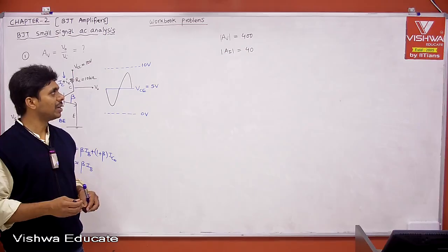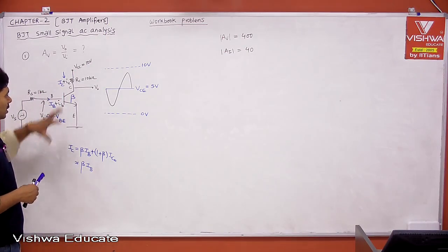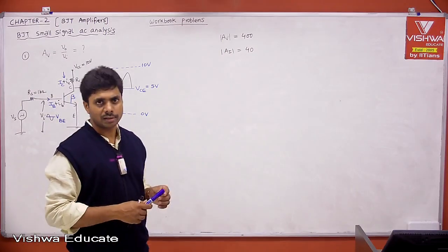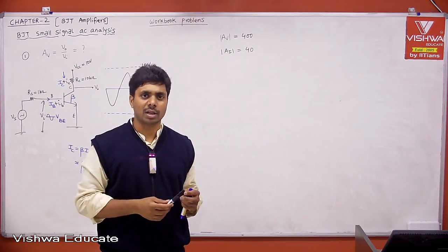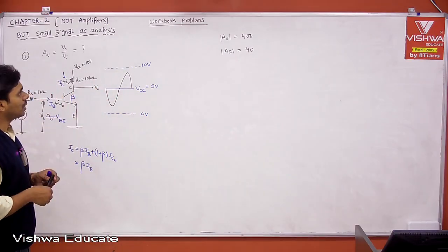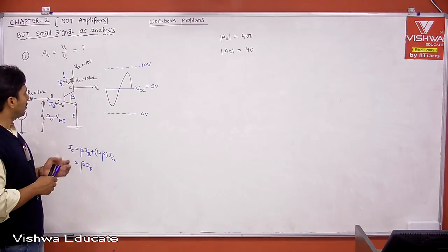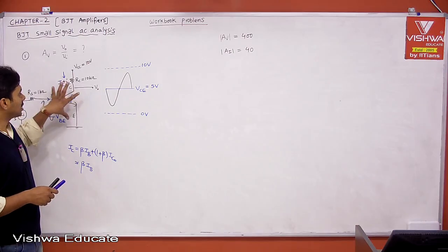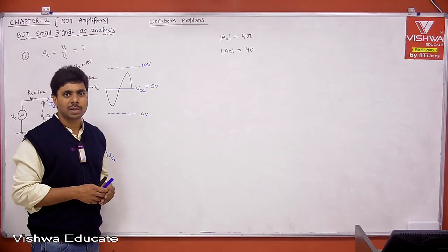Okay, then let me ask you. Definitely, if you want to improve, you can improve voltage gain from a single stage amplifier, maybe from 400 to 500 or 600. But we cannot get 400 to 40,000. We cannot get that much, right? Therefore, a single stage gain of 400 is not enough to get huge gain. Definitely we need two stages. When you take two stages, single stage gain 400, and if you take one more stage, 400 into 400, a multi-stage amplifier, right?